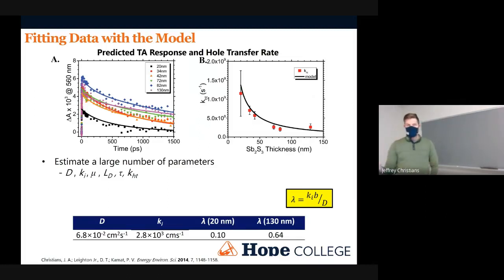We could then calculate a Biot number, which gives us the relative size of how important transfer at the interface, or the convection term, is relative to the diffusion term. Which one's winning? Which one's faster? Which one's slower? That's really one of the interesting things that we pulled out: you could figure out which of these processes is the slow step.